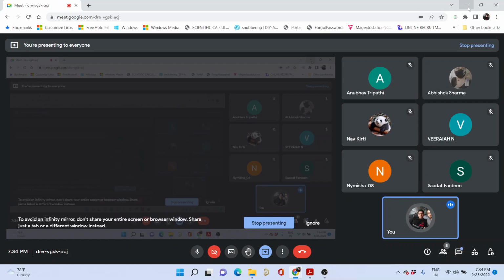For determining the frequency response. How do you manually find out the frequency response of a system? Replace it by j omega. Why do you replace it with j omega? Because the output is only to sinusoidal input. Correct. It is the output of a system to a sinusoidal input of a particular frequency.